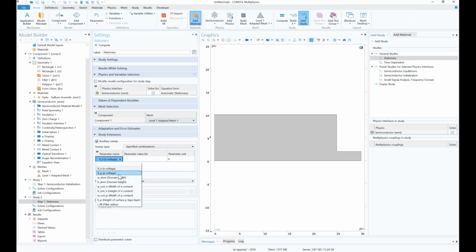Okay, so COMSOL always recommends that when you simulate a semiconductor device or material, you always run this continuation solver. That means you do not increase the voltage by a large number in one step. Instead, we start with 0, then slowly increase the value to what you want to obtain. In this case, with sweeping we can also get the IV curve, so it's also useful.